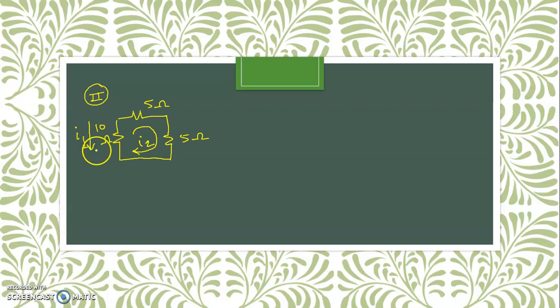This current is I1, which is downward. If this current I1 of the first loop and I2 of the second loop are in opposition, then as we are writing the expression for this I2, loop 2, the equation by inspection is minus. This negative sign indicates I1 is in opposition to I2.